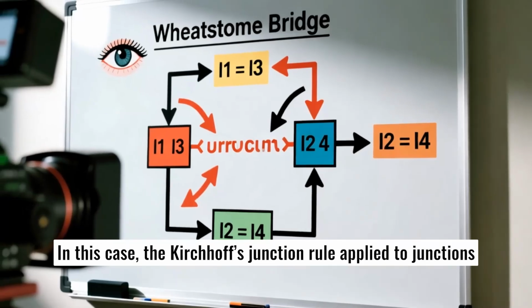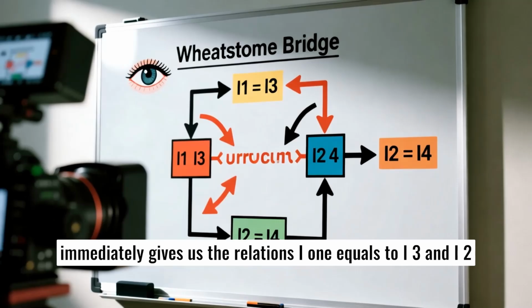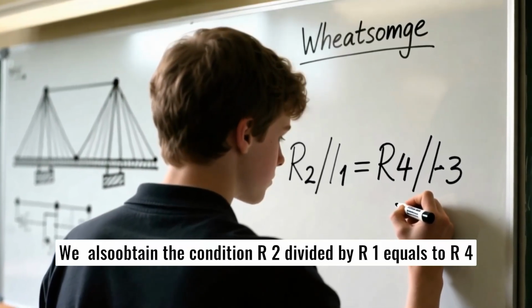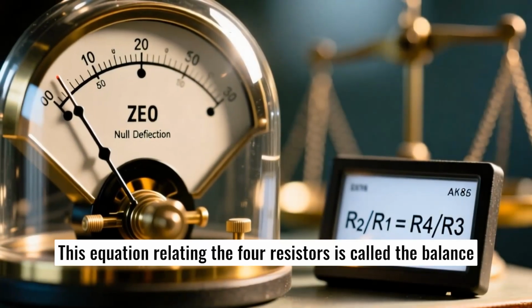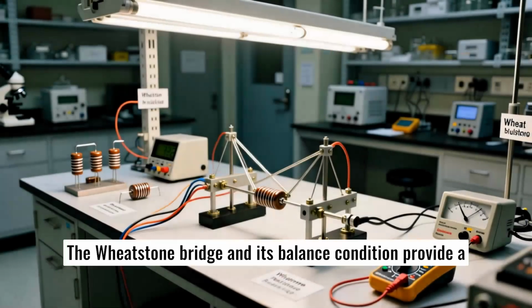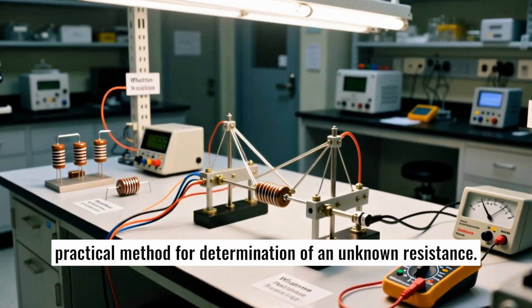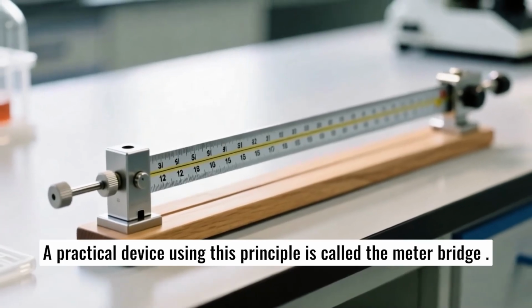In this case, Kirchhoff's junction rule applied to junctions immediately gives us the relations I1 equals I3 and I2 equals I4. We also obtain the condition R2 divided by R1 equals R4 divided by R3. This equation relating the four resistors is called the balance condition for the galvanometer to give zero or null deflection. The Wheatstone bridge and its balance condition provide a practical method for determination of an unknown resistance. A practical device using this principle is called the meter bridge.